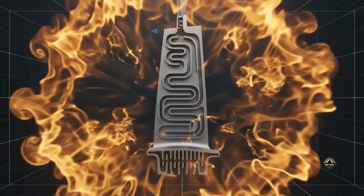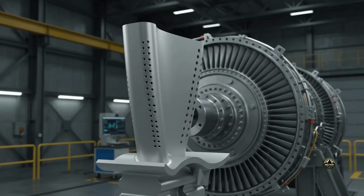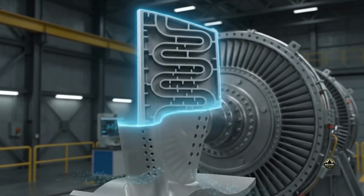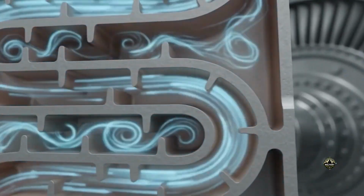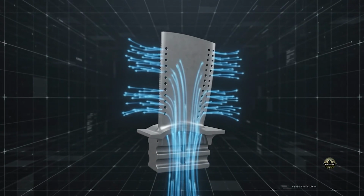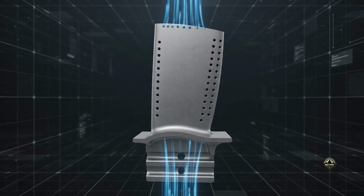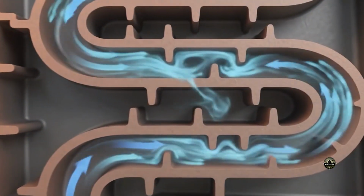Cooler compressed air from the engine is routed through tiny passages inside the turbine blades to carry heat away from the metal. Inside the blade, these passages can form complex serpentine channels. Ribs and special surfaces increase turbulence, improving heat transfer from the blade to the cooling air. Some of this cooling air escapes through tiny holes on the blade surface. This forms a thin protective film. It separates the metal from the hottest combustion gases.